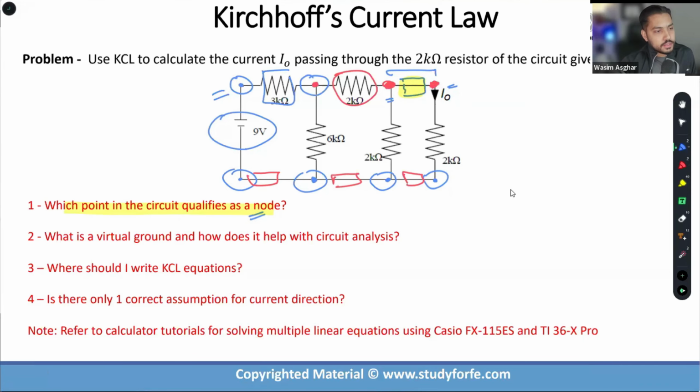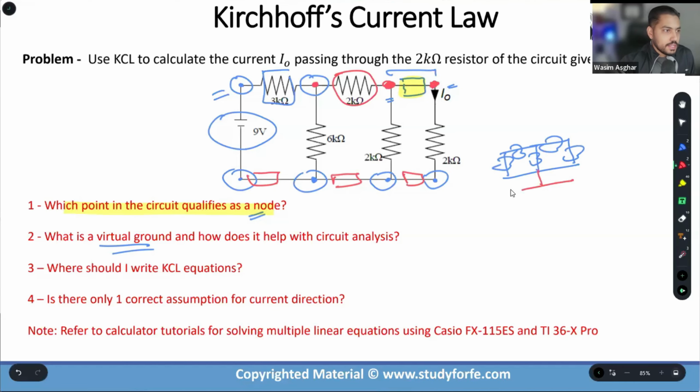Now, the second point that is connected to this first one is the concept of virtual ground. In some circuits, when you analyze them, you have one branch, two branch, three branch, components here, components here, and you may explicitly be given a ground. The fact of the matter is that ground is nothing but a common reference point. Okay. The same potential reference that can be used. And if you are not given a ground explicitly, you can still add a virtual ground. Okay. This is important.